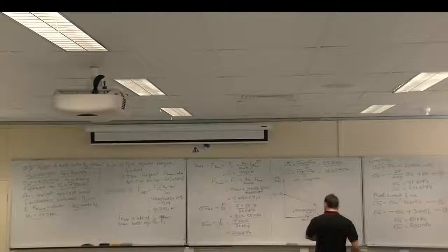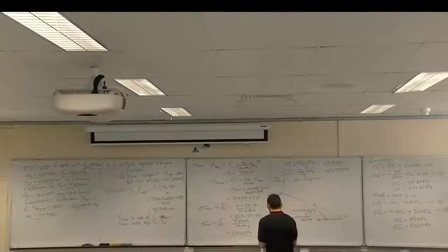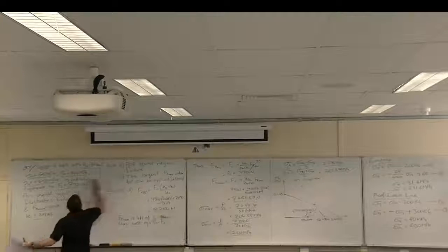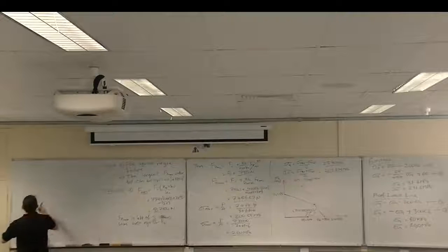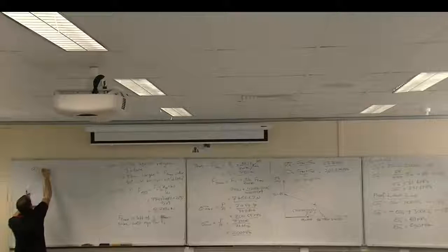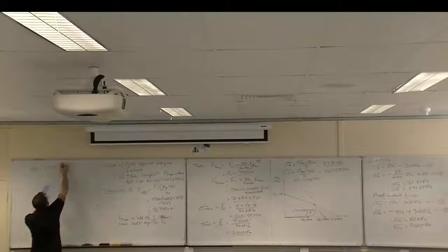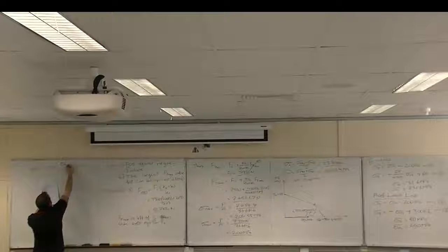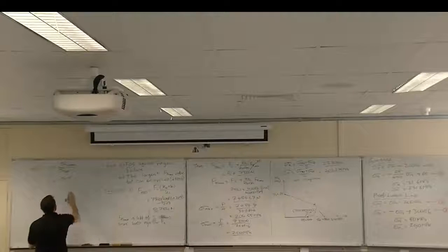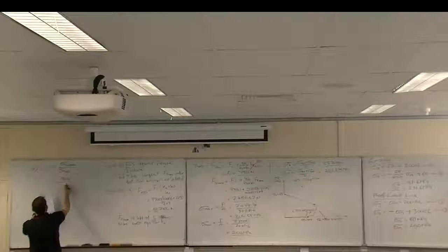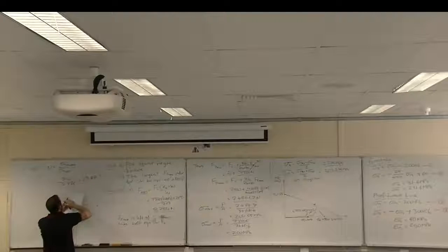So now, very quickly in our last minute. Alright, so for A, therefore n equals sigma A allowable on sigma A operational. The allowable is 31.6, divided by 2.275, and I get 13.87.